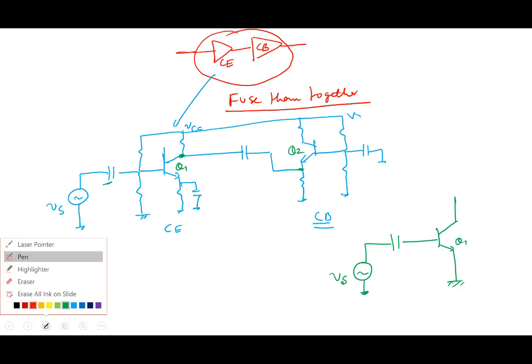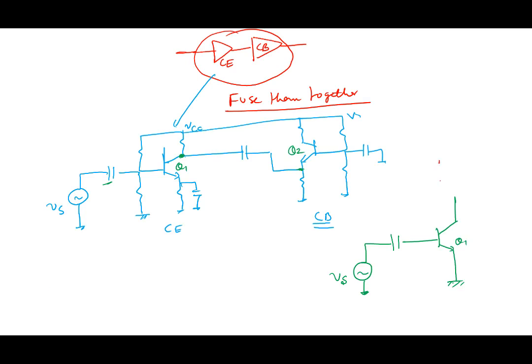So what I do is the following. On top I put the second transistor, this Q2. Note that Q1 is going into Q2, and there was a capacitor used here, but I remove the capacitor and directly couple it. Then the Q2 collector is connected to an RC here. There's a supply voltage here, and this is where we are taking the output, V0.